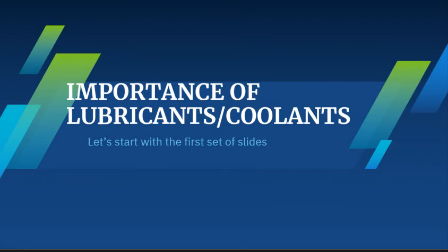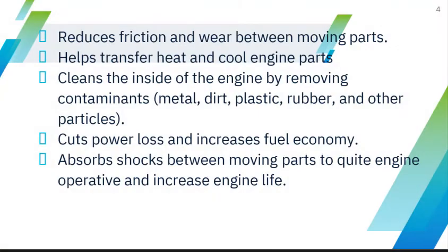So what's the importance of lubricants and coolants? They reduce friction and wear between moving parts. They help transfer heat and cool engine parts. They clean the inside of the engine by removing contaminants such as metal, dirt, plastic, rubber, and other particles. They cut power loss and increase fuel economy, and absorb shocks between moving parts to quiet engine operation and increase engine life.